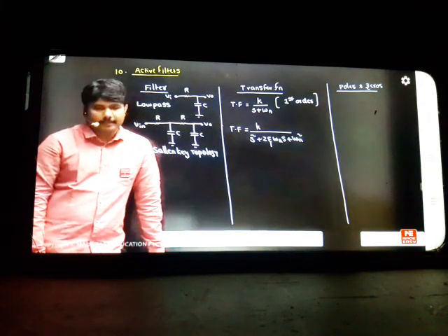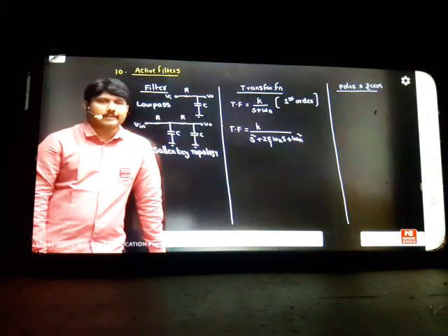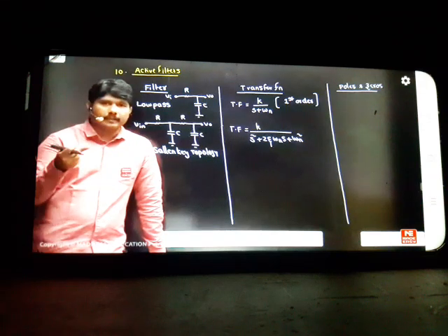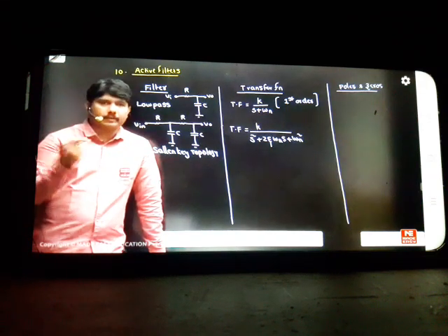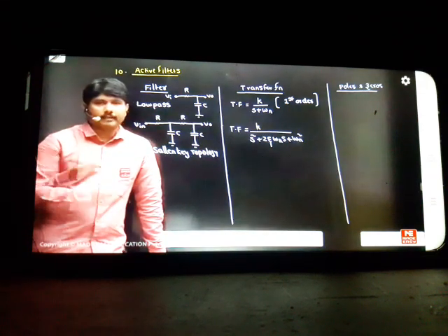You should have the standard basics first. K is the same constant, divided by S square, which comes because you have taken 2 low pass filters, plus 2 eta omega n s plus omega n square. Eta we call the damping coefficient, and the damping coefficient will decide the filter approximation, called Butterworth.